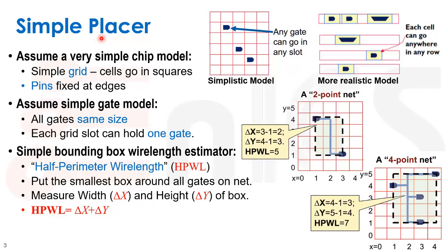We know that wire length is somehow proportional to the size of the chip. It's proportional to how far standard cells are away from each other. It's proportional to how slow we are, because we have to drive these long wires, and how much power we are going to be wasting, because we have to charge and discharge the capacitance of these large wires. So wire load is a good estimator that helps us optimize our placement. Is it the perfect thing? No, but I don't have a better answer for you today, so that's why we decided to take wire length.